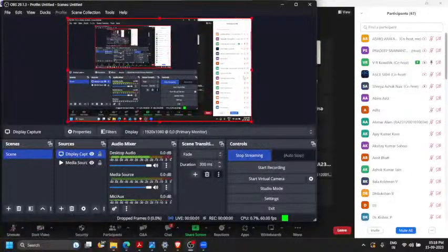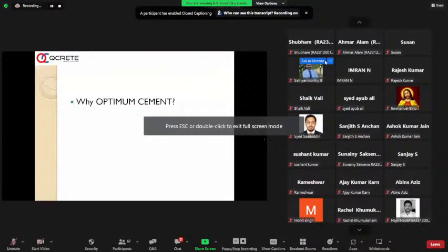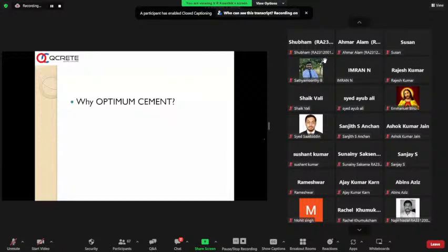Hence, ultimately the production of OPC per se is not a sustainable activity if we are continuously doing this. Over a period of time, we know in each country the limestone reserves get exhausted, and hence we are getting into problems. So we need to have control on the optimum content, and strike a level where, for what grade, how much cement content we have to use.